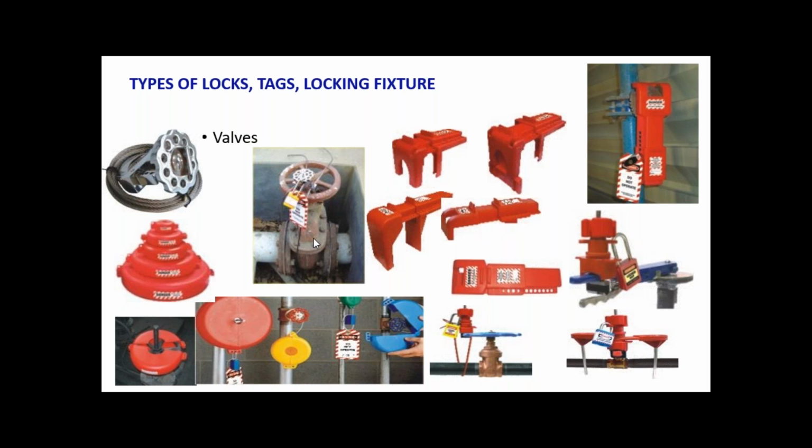So we are locking this valve. It means we are stopping or isolating the equipment or the system from the different types of energy sources. And we have applied the tags like do not operate these valves.